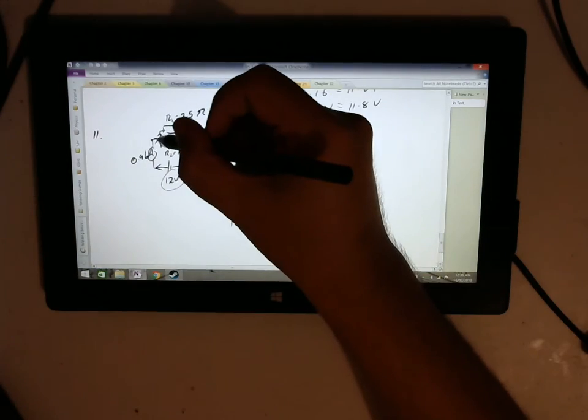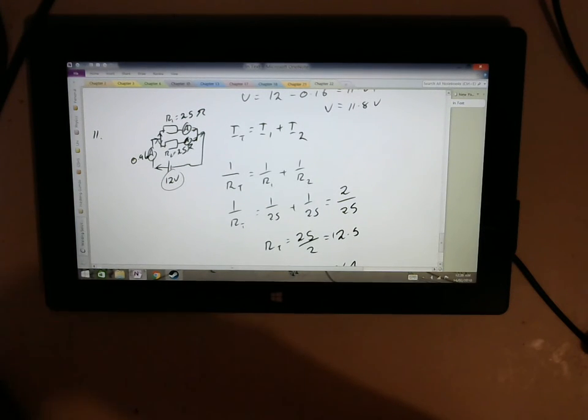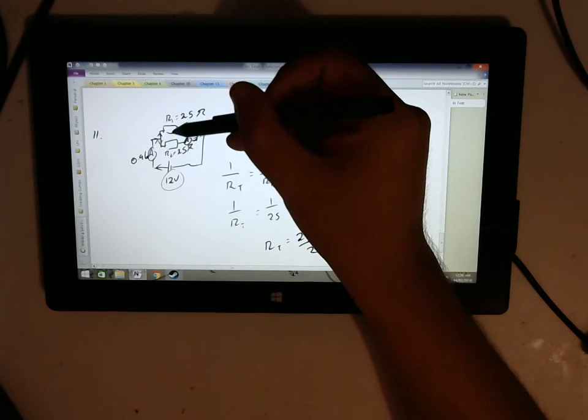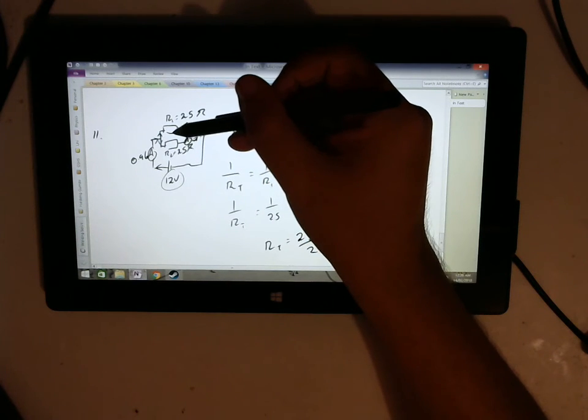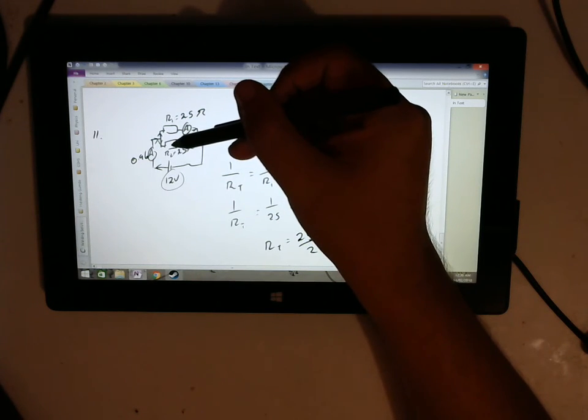And then it gets to here, it splits into two. So the two numbers, however much is flowing out, must equal 0.96. And being as they've both got the same resistance, it's intuitive that it should be the same number. If we were to halve 0.96, we'd get 0.48.